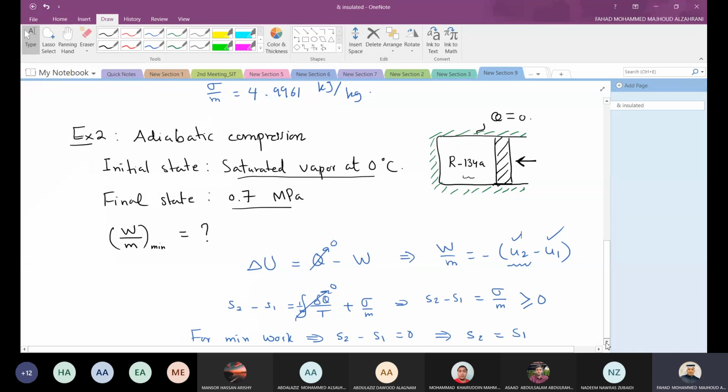If you remember the cycle, when we said the maximum theoretical cycle was for a reversible cycle, there is no irreversibility in the system. This is exactly the same thing. Here the minimum theoretical work is the minimum I can apply without irreversibilities, because irreversibilities put more resistance to applying more work. And this comes from entropy. The entropy balance tells you, if I'm not generating irreversibilities, do I generate entropy? No. For internally reversible, I don't generate any entropy, so I consider it equal to 0. So the minimum theoretical work is when you have no entropy generation.